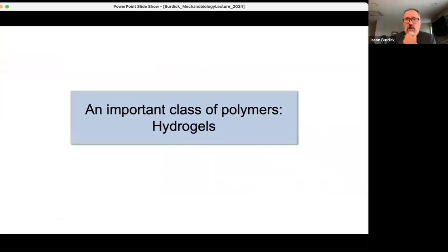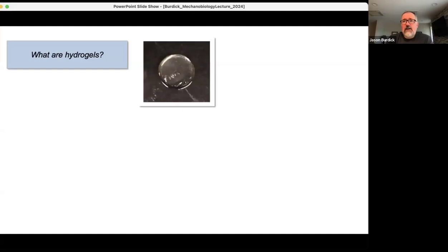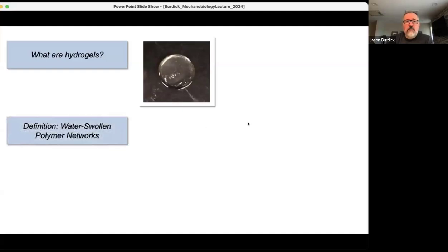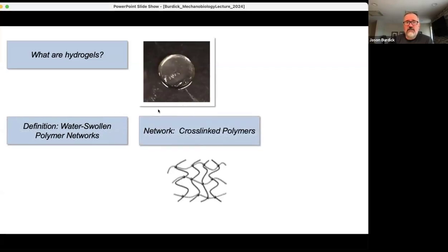Then let me get through hydrogels and I'll pause, see if there's some questions before I talk more about applications. Again, I've already mentioned hydrogels, but these are water-swollen polymer networks. So you just think of these as made from polymers that really like water. So we can dissolve these polymers in water. And then if we link them together or cross-link them through different types of junctions, they won't dissolve when they interact with water, but rather they'll just swell.